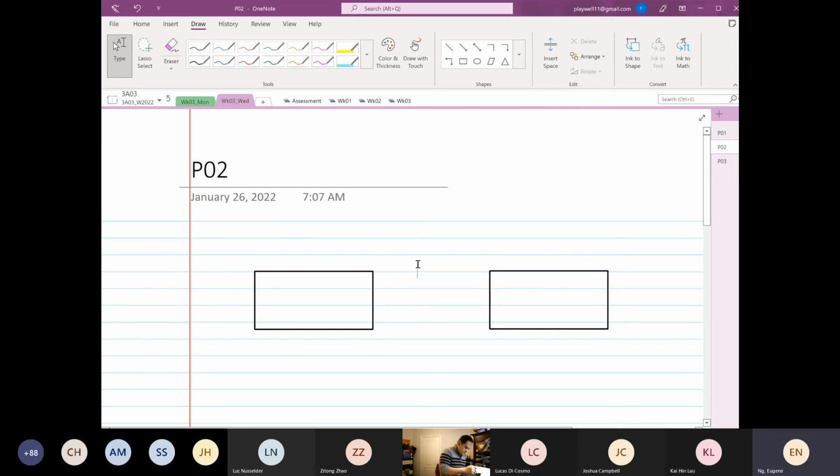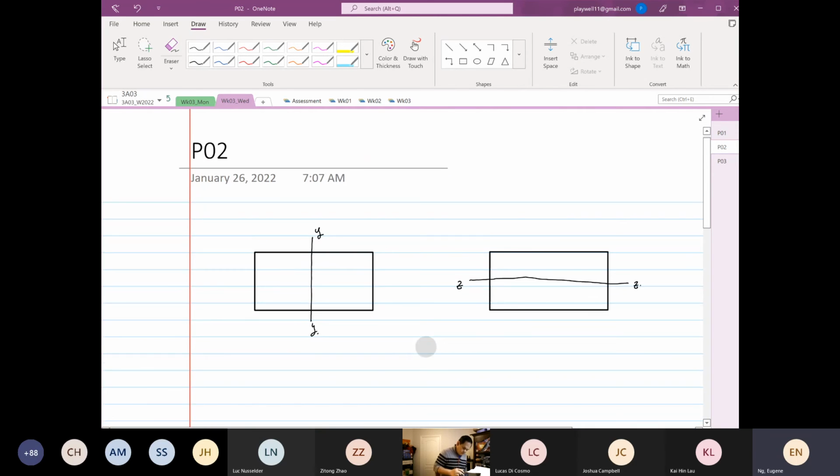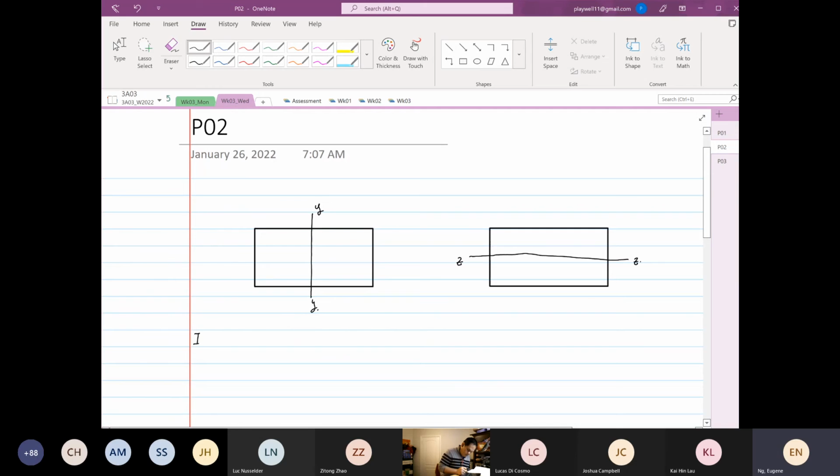Okay, so I'm going to find Iyy first. So this is our Y axis, and over here, this is our Z axis. So we're going to find our Iyy. Because it's exactly at the centroid, the formula is width times depth cubed over 12. Izz is also width times depth cubed over 12.